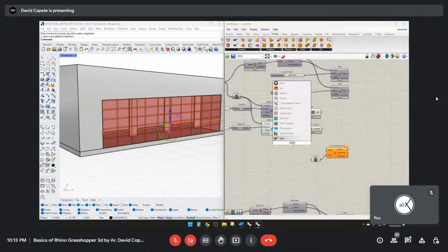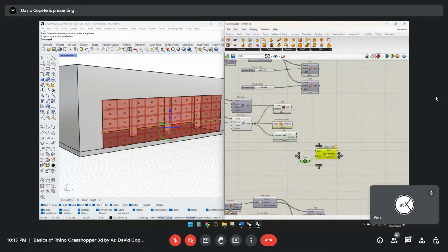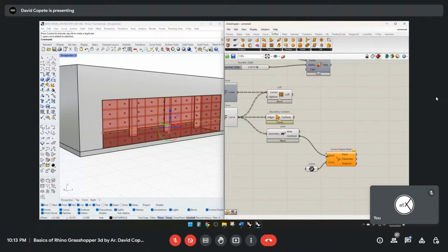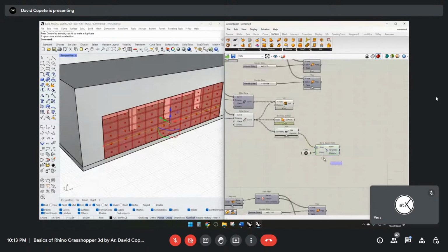So I'll go to an area component, plug in these rectangles into the area component, which gives me the center point. Now those centroids will go into the point, and I'll flatten the input so it comes in organized correctly. Now notice that all this component does is it calculates how far this line that I created is to the grid.